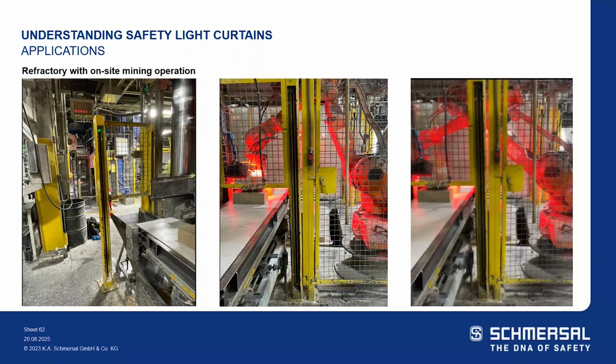They were originally using light curtains from Allen Bradley, the 450L, their universal transceiver module that accepts transmitter receiver plug-in modules, or they were using the Omron MiniSafe of various sizes and resolutions. But they were having problems with tripping issues on both the Allen Bradley and the Omron due to interference, due to EMI noise. The light curtains would trip and require reset intermittently, sometimes multiple times a day, sometimes multiple times an hour.